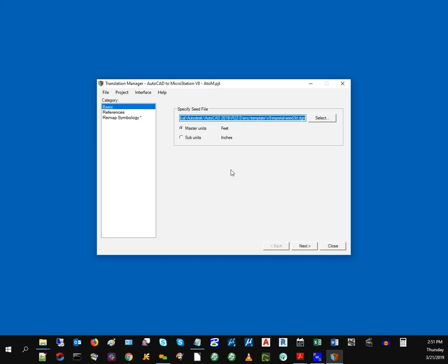If they were regular cells placed all over the drawings, when translated to AutoCAD using the AutoCAD translator, each individual cell would come in as an individual name. In other words, if it was a bolt cell, the first instance would be bolt 1, the next instance of that same regular cell would be bolt 2, and so forth.